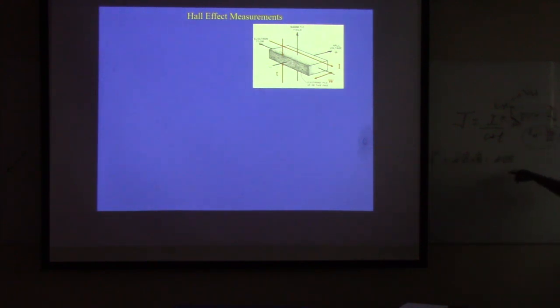So this is the force on the electron. This is going to be balanced by the Hall field. What if the Hall field is E_H? What is the force? E times that Hall field. So you can see the E and E cancel, and then you get v as the Hall field divided by your B. Or if you want to write E_H, you can write it as V_H divided by W. Yeah, V_H and E_H are connected this way, right? So that is my v.